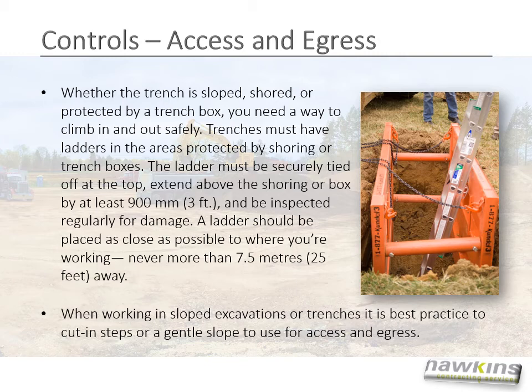When working in a sloped excavation or trench, it is preferable to cut in stairs or a gentle slope. This type of access and egress is safer and more practical than ladder use.